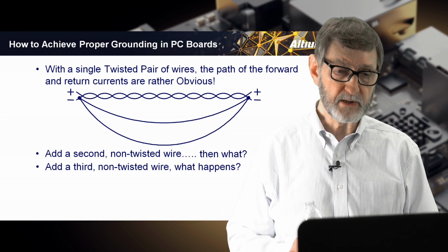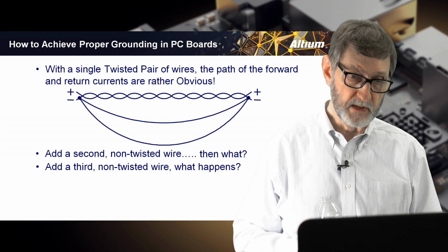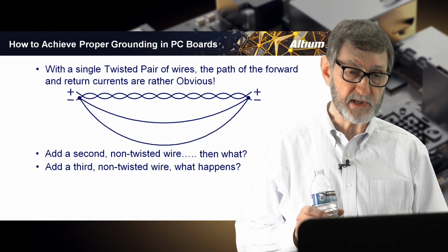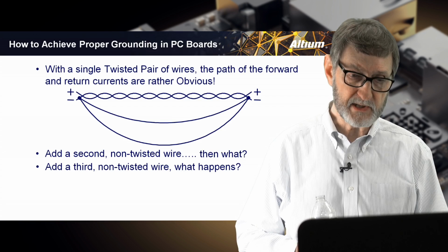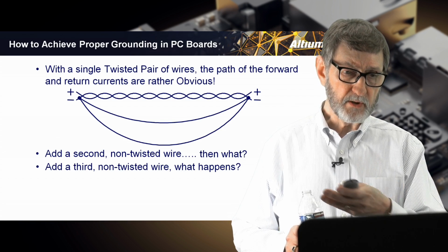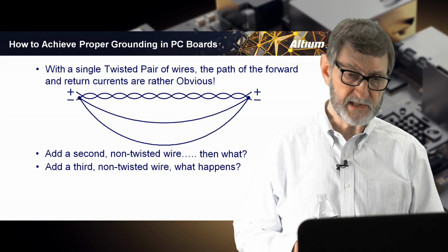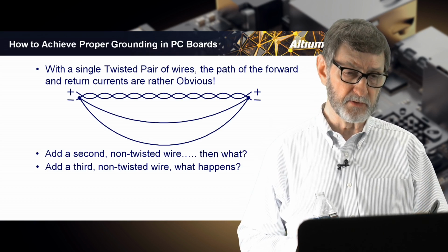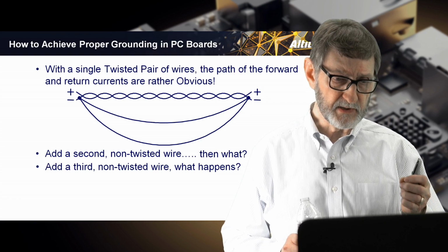This will be what we call a classic ground loop. Ground loops, by the way, exist at low frequencies. They don't exist at high frequencies, and you'll understand why in a moment. The current would split equally among all 3 of these at DC. Again, imagine a signal generator hooked up to this circuit.